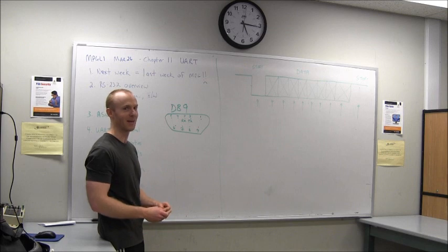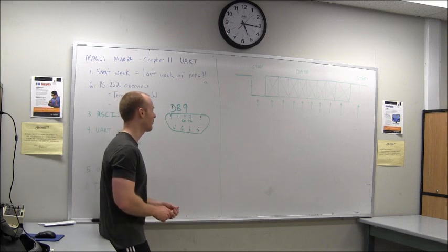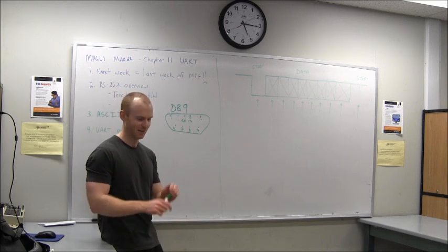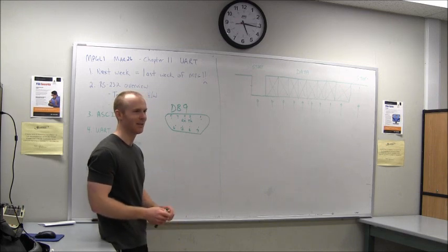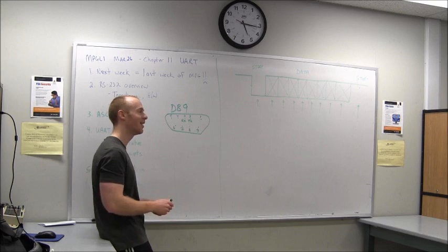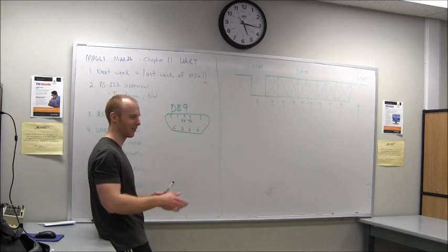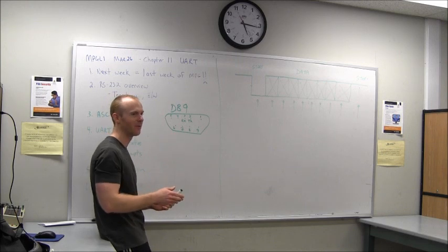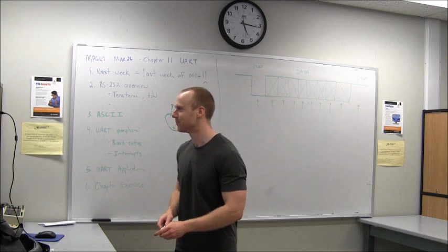I've also killed many, many hours troubleshooting UART firmware when it's someone who has put in a null modem cable. So I'm quite religious about putting a piece of tape that says this is either straight through or null modem cable. I'm going to build a little device, so you'll see it on the Engenuics page. That's just a quick plug-in check for that, because you can waste hours figuring that out. Some null modem cables actually have an X on them, or will say null modem. Buy those ones, so then you won't be confused.